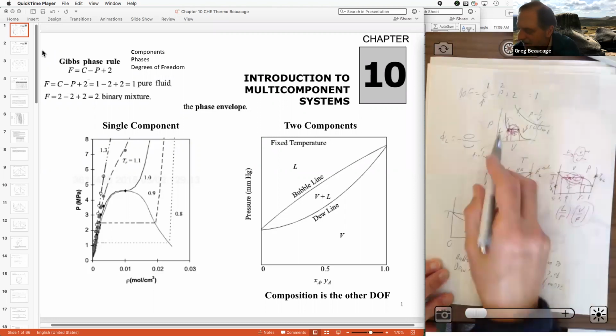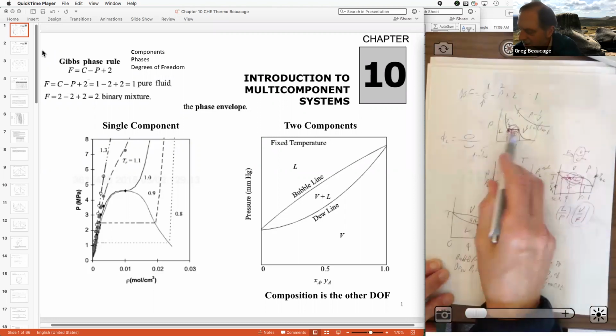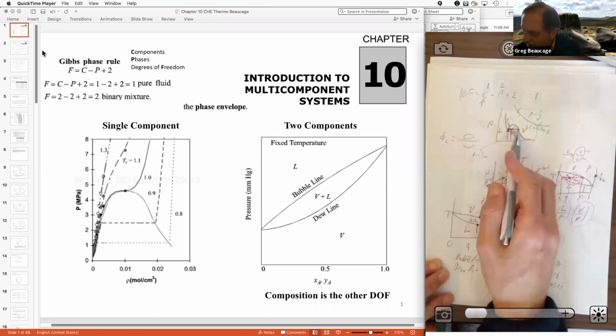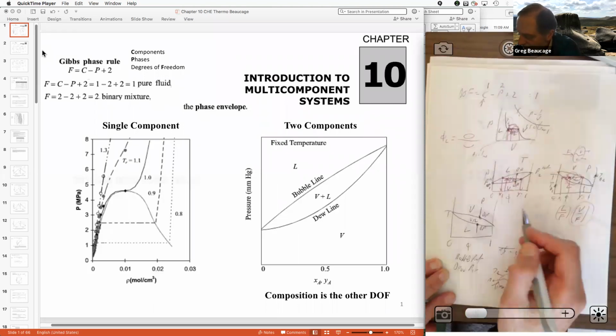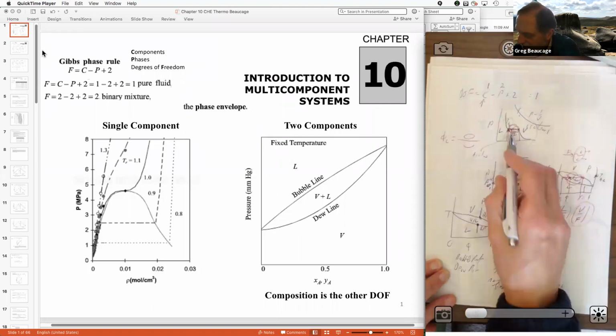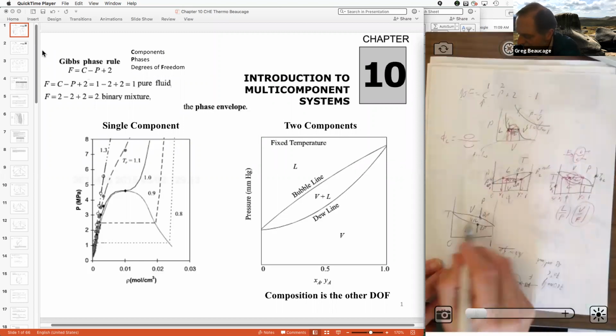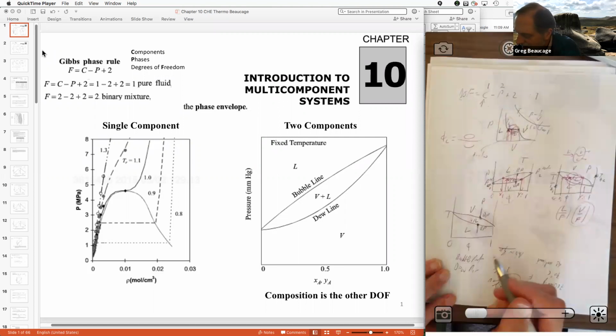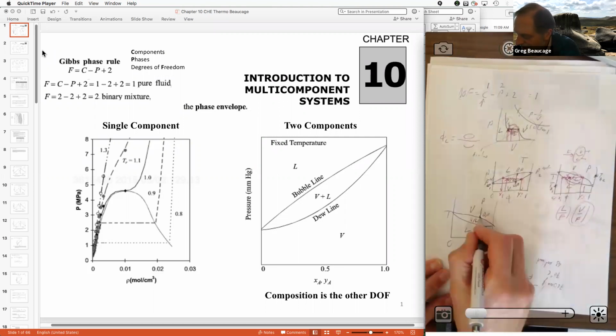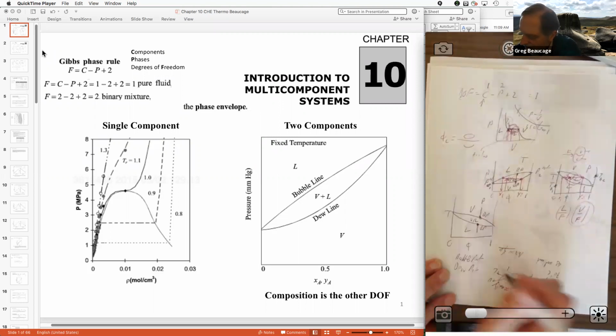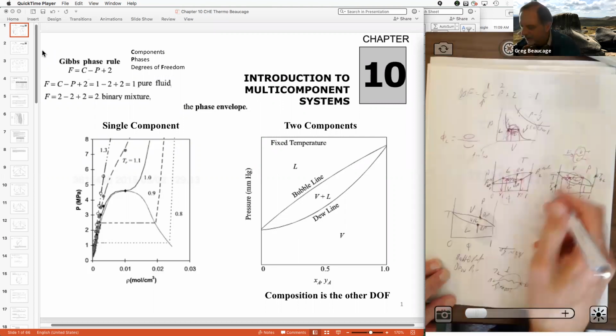Here with a single phase, you just have one pressure and one temperature where you get the equilibrium. You can have a liquid vapor mixture, but it's going to be at a single temperature and pressure. Here, there's two of each. Right? There's an X temperature for the liquid state and a Y for the vapor. That's kind of how this looks.